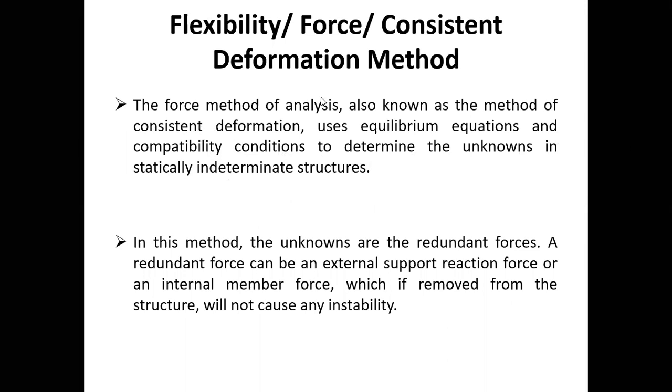We know already that in terms of analyzing a structure, we are concerned with equilibrium conditions, and the number of compatibility equations exceeding the equilibrium conditions is the degree by which the structure is indeterminate. So we'll be doing that in the force method of analysis. In this method, the unknowns are redundant forces. Obviously, redundant forces are the unknown forces.